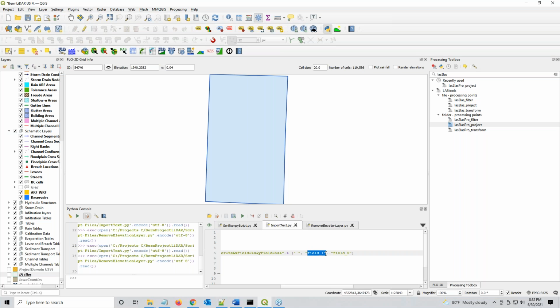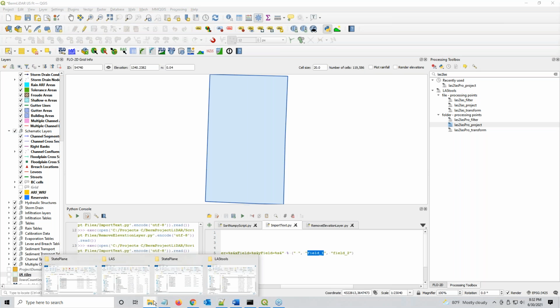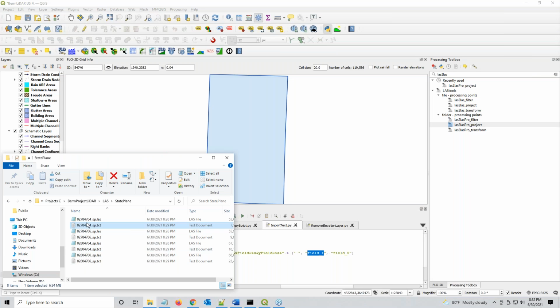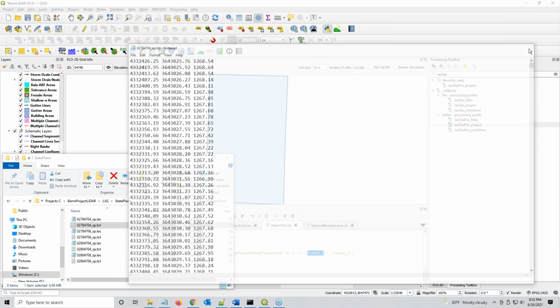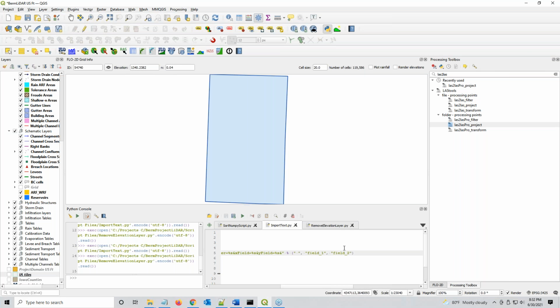And then instead of having to make this, you saw right away that that data didn't have field names. So instead we just said field 1 and field 2 are X and Y. And you can see that right here, field 1 and field 2. So that's super easy to set up. And again, if you wanted to use this, just download it, change your file path, and then it's going to take and load, hang on a second, an elevation layer using this QGIS vector layer.